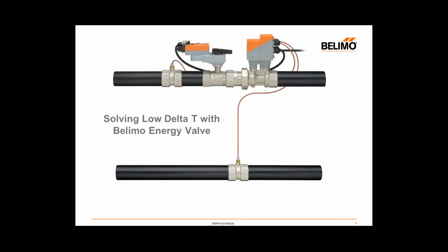Or give you an introduction to the Belimo energy valve. If you're not familiar with this technology, the Belimo energy valve is an electronically pressure-independent control valve with a fully integrated and BACnet connected BTU meter. That seems like an awful lot of stuff to jam into a control valve, but I'm going to spend the next 20 minutes or so trying to explain to you why we did that and how it can benefit you or your customer. So let's go ahead and start obviously with the title.